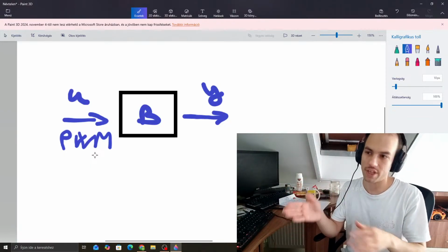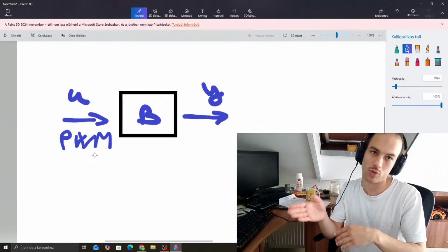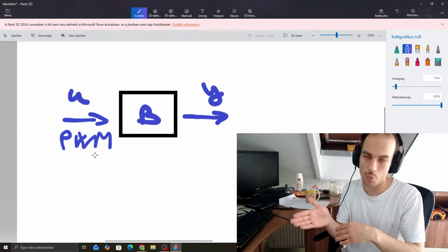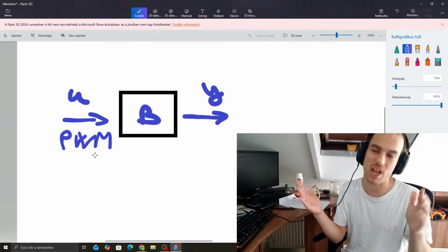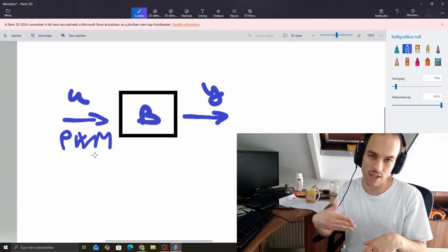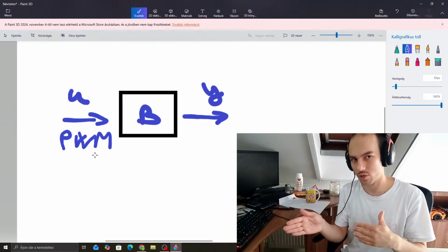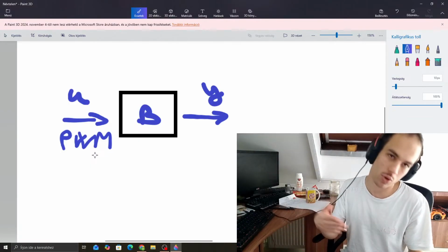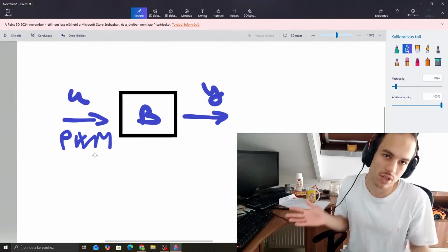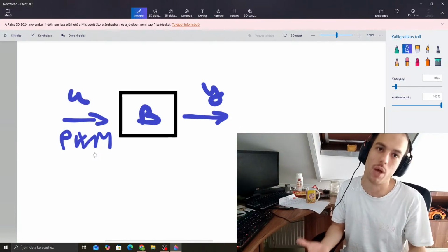The whole thing is that you quickly open and close it, and the percentage is how much it is closed versus how much it is open. If you have a given period, let's say 10 seconds, you open it for 1 second, close it for 1 second, and so on. That means it is open half the time and closed half the time, so 50% of the amount is going to come out, meaning it is 50% PWM.